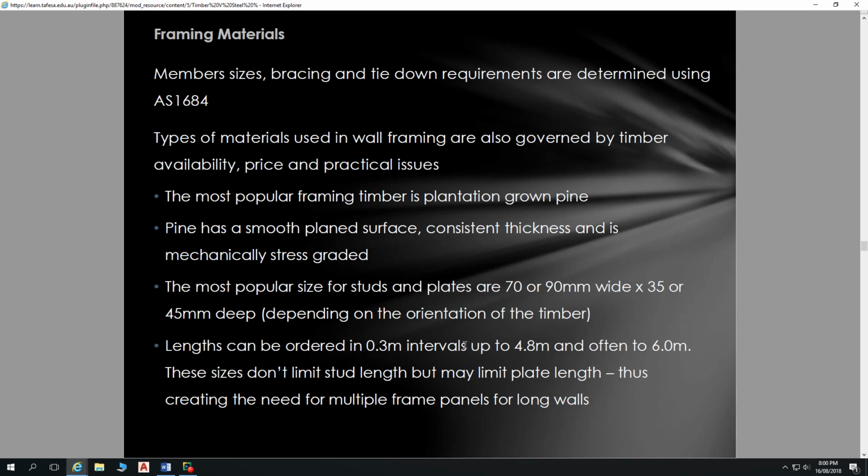It takes a lot of mucking around to work out those economics in building. So you think, all right, let's do our ceiling height at 3 meters, because that's a whole lot of 6 meter 90 by 35s cut directly in half. Fantastic. Except when you get to the size of your plasterboard sheets.